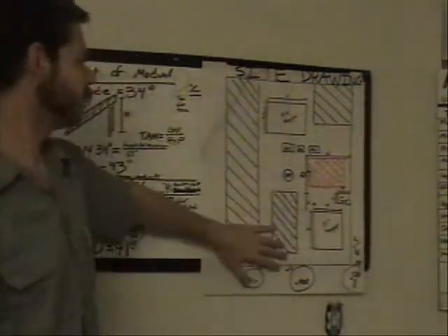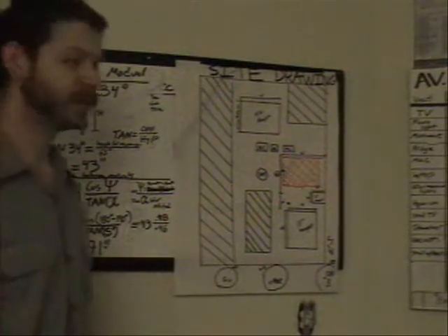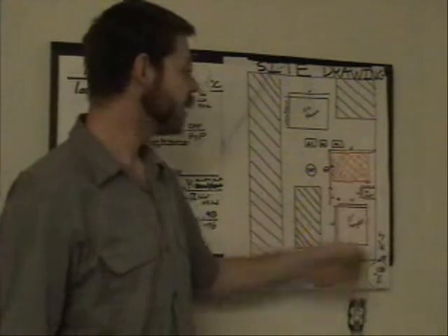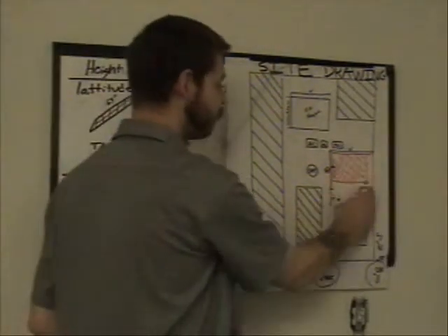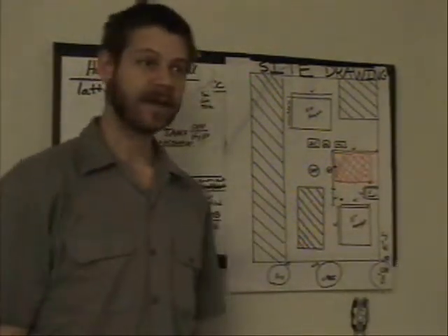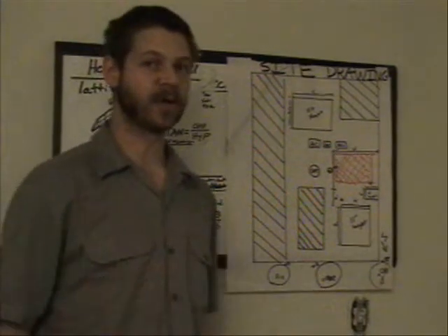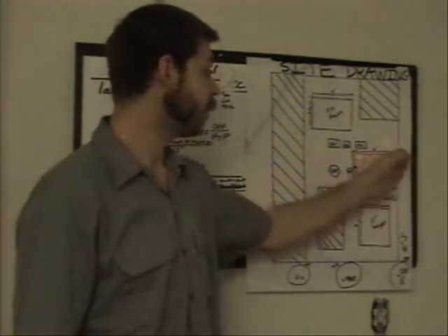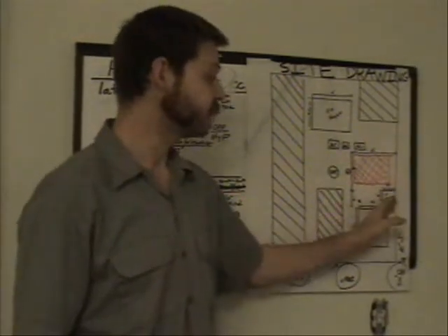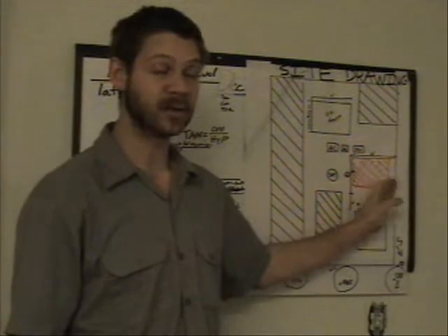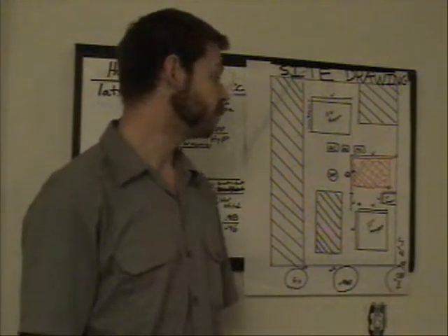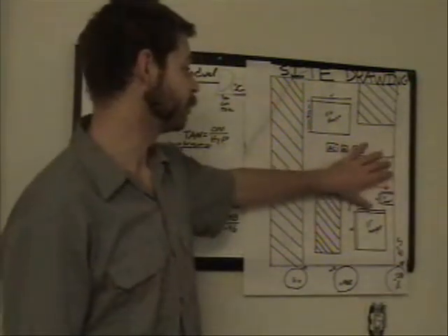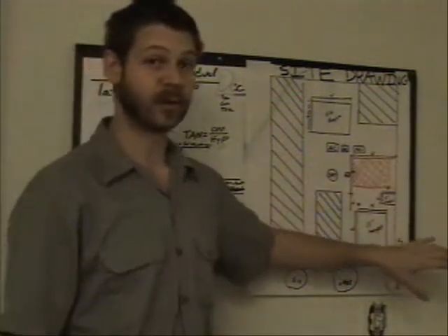On this side drawing, I just want to talk about a few other things, a few of the restrictions. We determine the shading, we determine the area. There's an area right next to the edge of the roof called an easement. Depending on your local code, you may need an easement all the way around your array. You may need an easement just on the side closest to the edge of the roof. But check your local code and make sure that your easement is included when you determine how much area you have for your solar array.